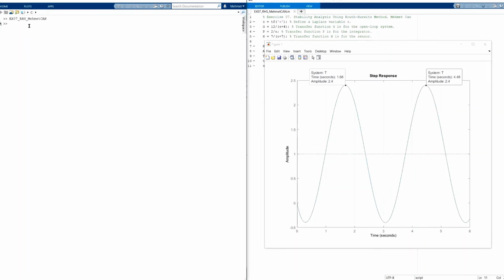Okay, now let's calculate T oscillation, just from the measurement from the step response. So that is 4.48 minus 1.68, which is 2.8. What we had was 2.78, which is really close, because I just look at it with my cursor here, and it is maybe not really that accurate. So I've already found that the oscillation frequency is correct.